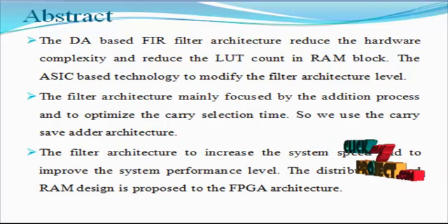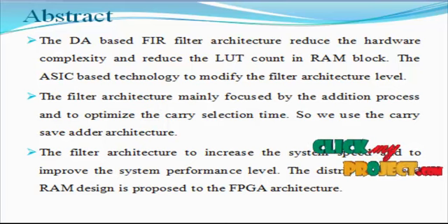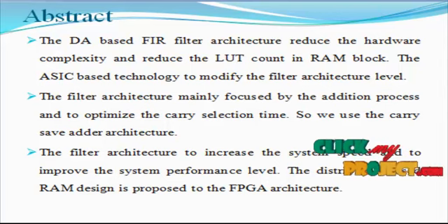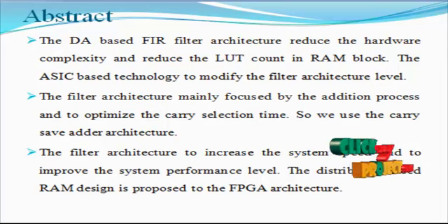The brief presents an efficient distributed arithmetic based approach for the high throughput reconfigurable implementation of finite impulse response filters whose filter coefficients change during runtime. Conventionally, for reconfigurable DA based implementation of FIR filters, the lookup table based DA units are required to be implemented in RAM, and the RAM based LUT is costly for ASIC implementation.